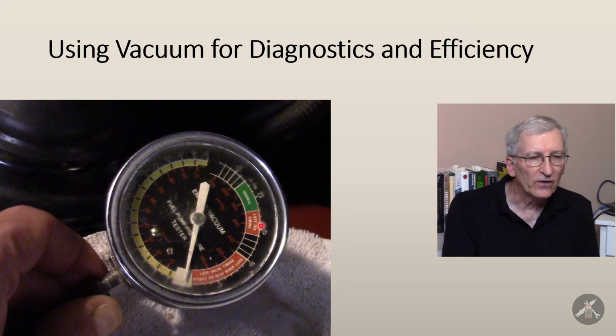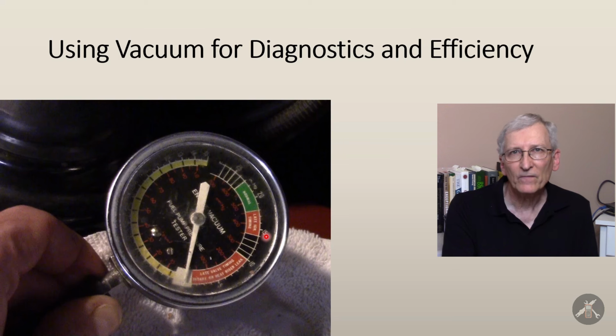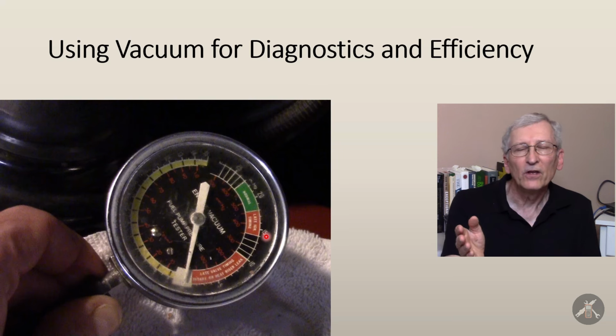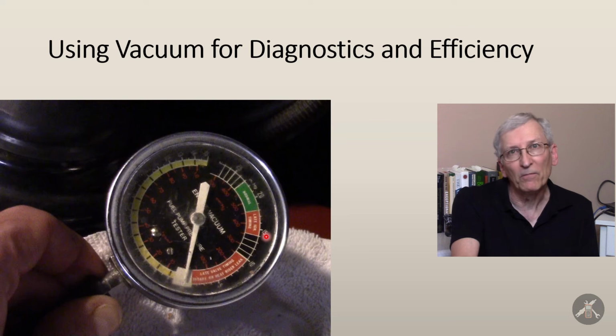Here where it's red and it's going around 15, it says, hey, late ignition timing. Because if you didn't have your vacuum advance on, or even if you had, most of the cars, until you got into the emissions era of the 70s, where the manufacturers were deliberately retarding timing in order to get emissions in line, then those vacuum numbers would start to drop.